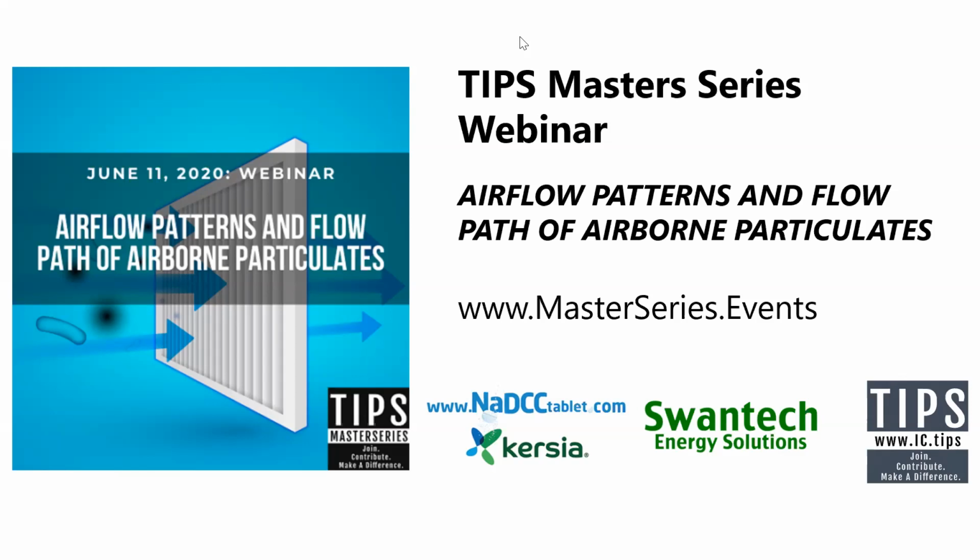Basically, depending on the wind patterns around your building and wind direction and wind speed, some of these openings will act as supply and some of these openings will act as return or exhaust. So try to understand that. Again, cross ventilation is very popular. If you have the opposite side windows, just open those. It can move the air from one place to another.